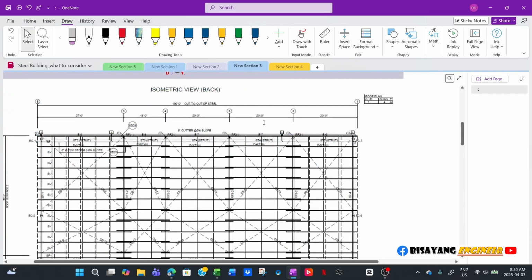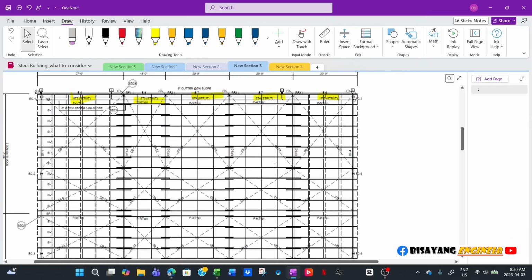So basically, one of the reasons why this particular frame has a separate strut is because the load is larger than the other, because this is designed as a post-disaster building. And then for seismic, you increase the importance factor, which will increase your lateral load from a normal building.